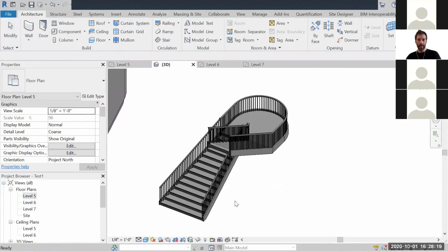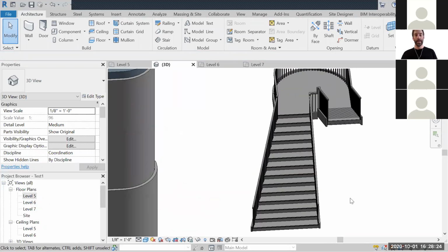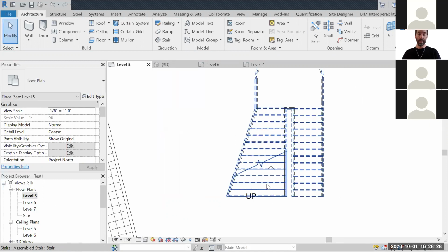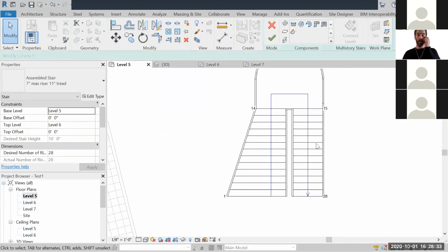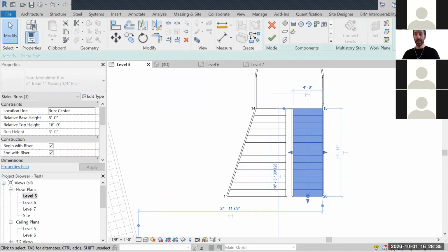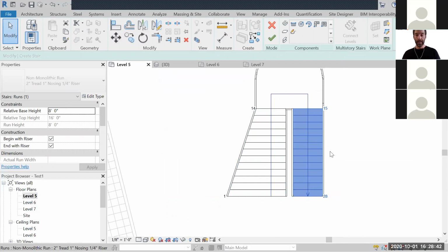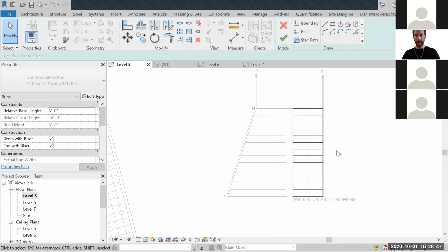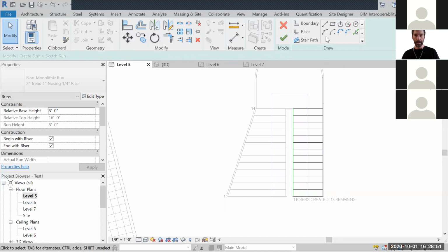So many times a step is a little bit bigger in the beginning, or at a particular angle, you might need to do this. It's very useful. Again, select the stair, edit the stair, select the component you want to change. You go to Tools, Convert. Once it's converted, it's converted. I'm just doing the 3 pieces. Select the converted piece, edit sketch, and you can change the green line for another line, such as an arc.